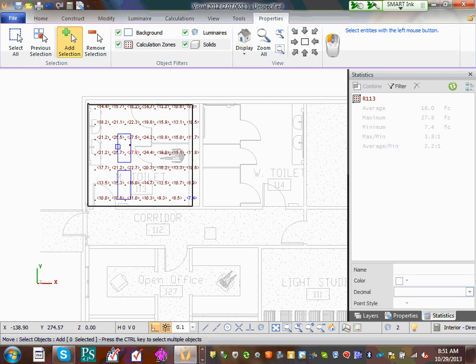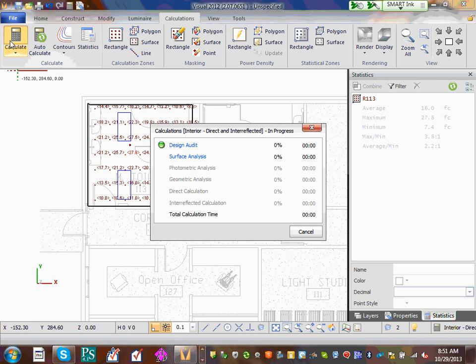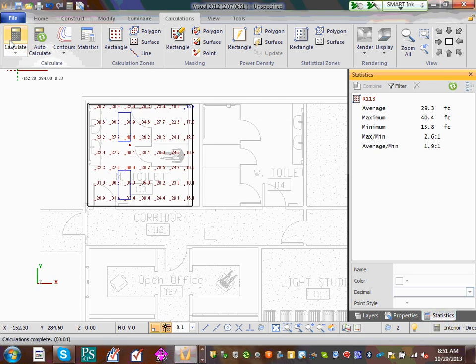Click on this fixture. Right click and move it slightly. I want to put one here and one here. I don't know if that's the best design or not. So I copied and moved another fixture and go back again to calculate and hit calculate. Gentlemen, you're getting into the details now. Copy, move, and so on. I have 29 with two fixtures. Two fixtures, 29.